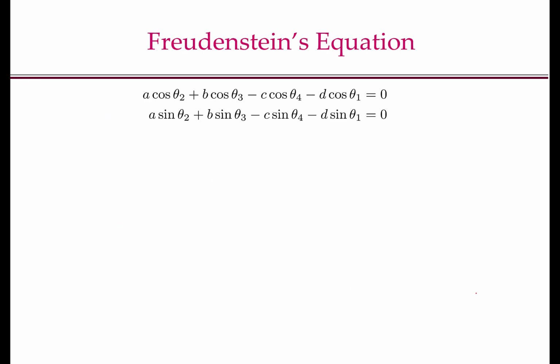Those of you who have looked at the textbook may have noticed that the way we solved the position kinematics problem for finding theta 3 and theta 4 looked a bit different from the textbook. The way I presented the 4-bar solution is to first introduce solutions of some general trigonometric equations and then show that the 4-bar equations are an instance of this general form.